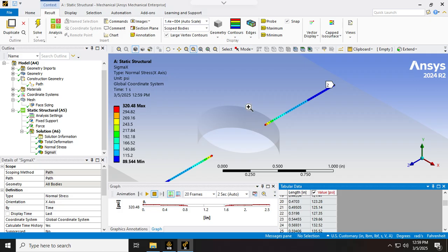If this bracket is too thick around the center where my path is, we're going to have a plane strain condition, not on this side, not on the hole, but internally. But if it is thin, we're going to have a plane stress condition.